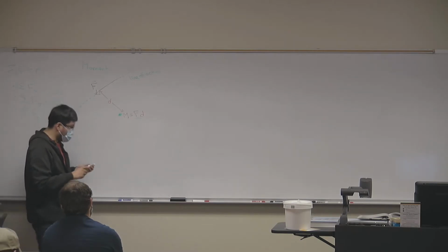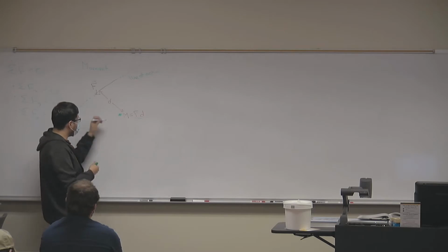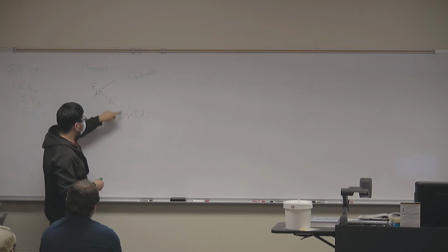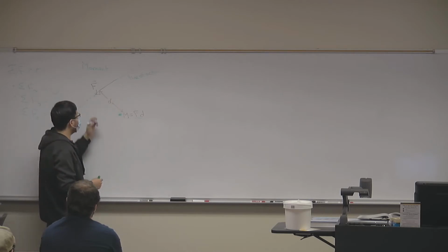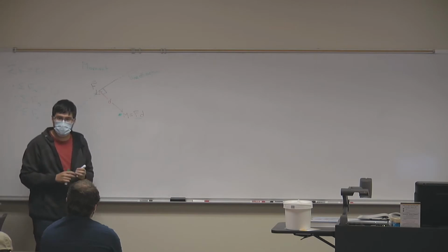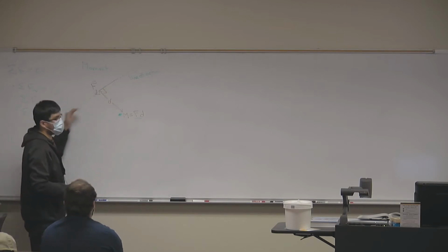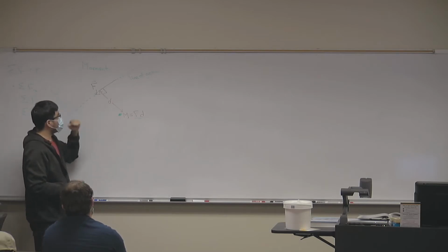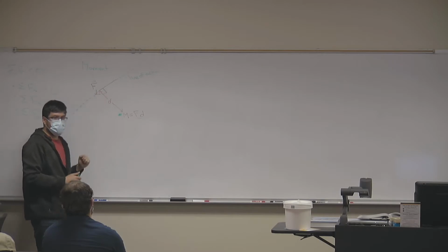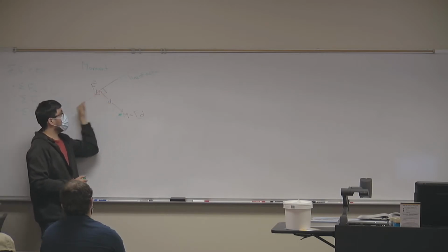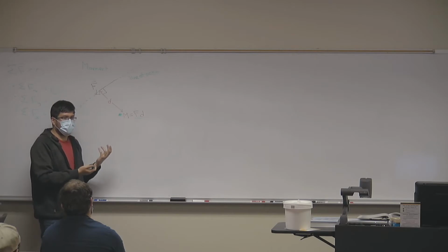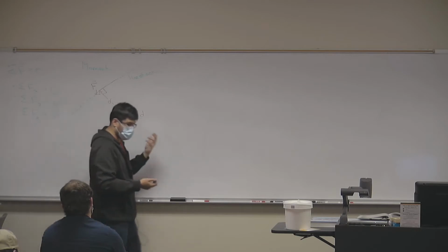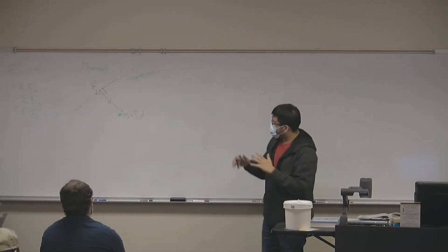Now the question is, how do you measure that distance? Would I measure my distance like this, like this, like this? So just to make things easy for you, you will always measure the distance between your point and your line of action as a perpendicular distance. So if you have a long line of action, and you want to find the moment about a point of interest, you want to choose the distance that provides a 90-degree angle between your point and the line of action. And this is essentially the shortest distance to the line of action. Okay? So shortest distance, 90-degree angle, and that is how we calculate moment.